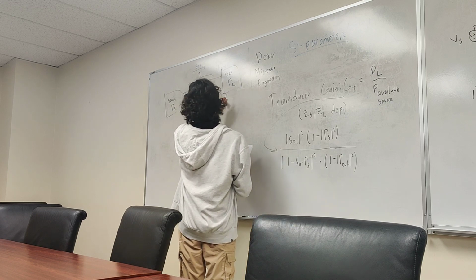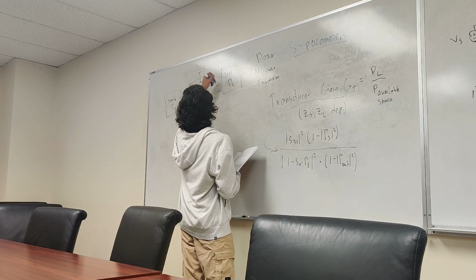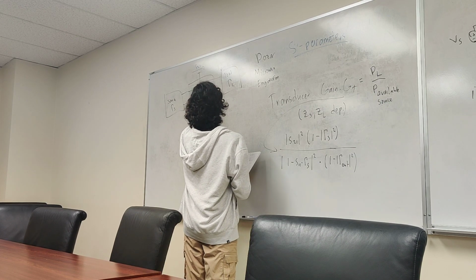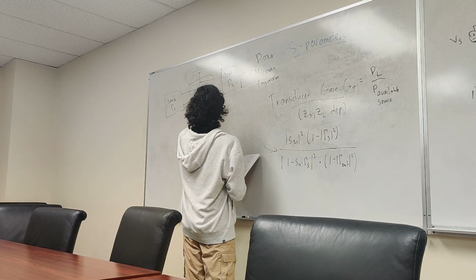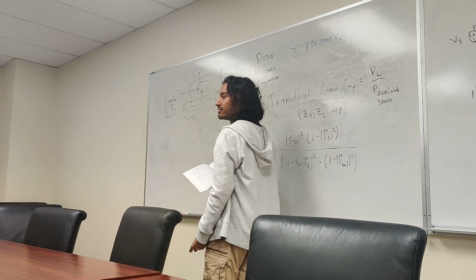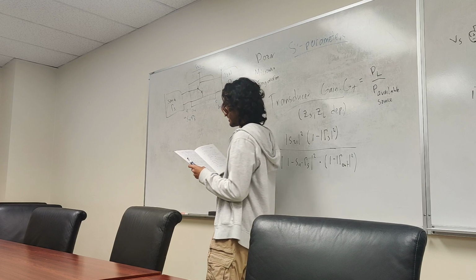That's one thing. Whatever gets initially transmitted goes over here to the output of our BJT network and hits the load. By the way, the top parts I'm using as forward, the bottom path reverse, right? So it gets reflected, it's going to become S21 times gamma L. We're good there? Okay.